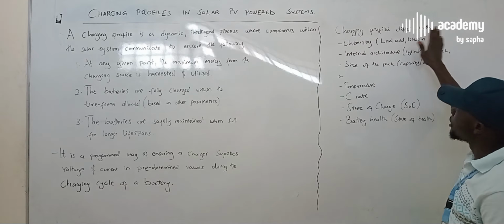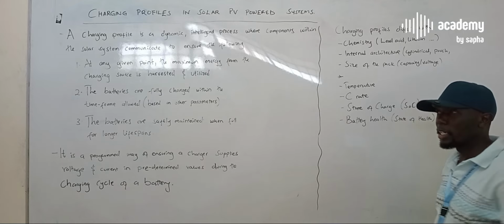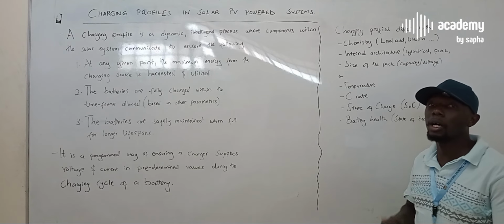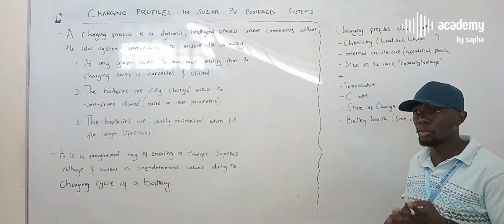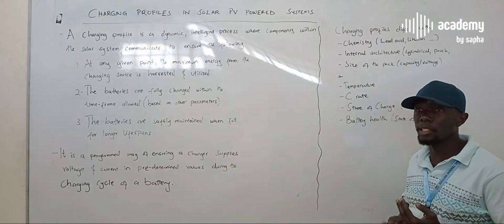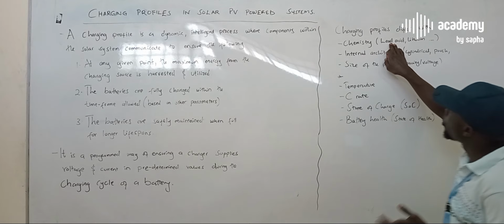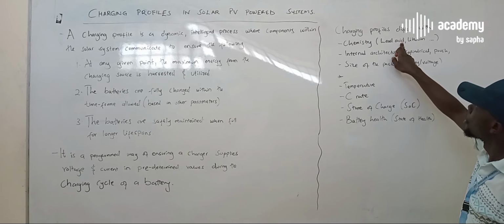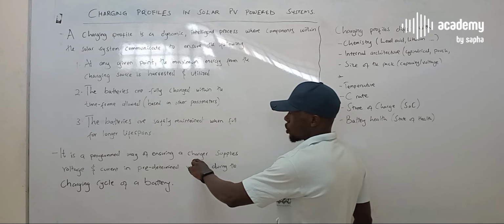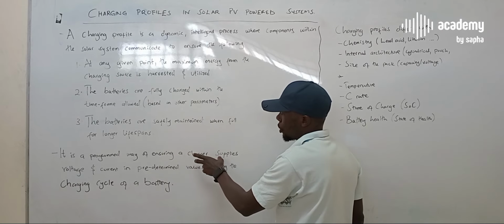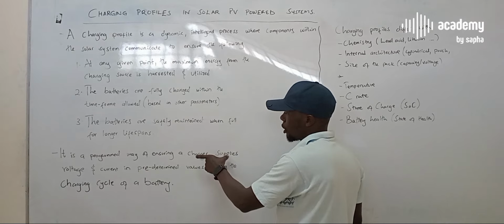The charging profiles differ with the following. Number one, the chemistry. The charging profile of a lead acid battery is different, and even within the lead acid battery, the different sub designs. We've got the flooded, the gel, the AGM. So when you change the chemistry between lead acid to lithium, you are also supposed to change the charging profile, or the program that controls the charging profile in the charger.